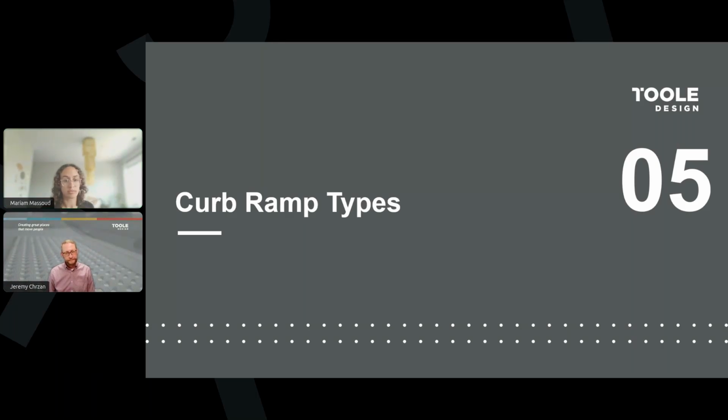Okay, very good. And last question. If you warp the gutter and raise the gutter plate, how do you not trap water? So the slope of the flow line will still remain constant. It's altering the slope in the direction of a pedestrian crossing. And so you have a few levers to alter.